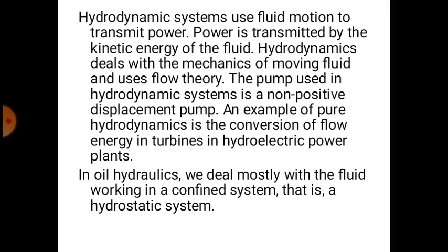Hydrodynamic systems use fluid motion to transmit power. Power is transmitted by the kinetic energy of the fluid. Hydrodynamics deals with the mechanics of moving fluids and uses flow theory. The pump used in a hydrodynamic system is a non-positive displacement pump. An example of pure hydrodynamics is the conversion of flow energy in turbines in hydroelectric power plants. In hydraulics, we deal mostly with the fluid working in a confined system, that is a hydrostatic system.